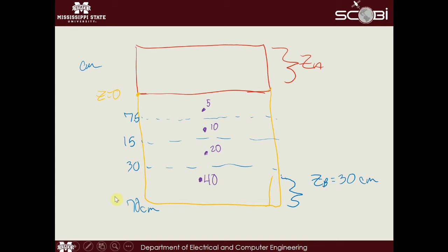Okay, so with all that in mind, what the discrete slab function does is it assumes that whatever volumetric soil moisture was at 5 centimeters beneath the soil moisture profile, well, whatever that was, that is the dielectric of this whole slab. It's now a 7.5 centimeter chunk. And then for the next layer, the one at 10 centimeters represents the soil moisture layer between 7.5 and 15 centimeters, and so on and so forth all the way down. So that's what the discrete slab is doing.